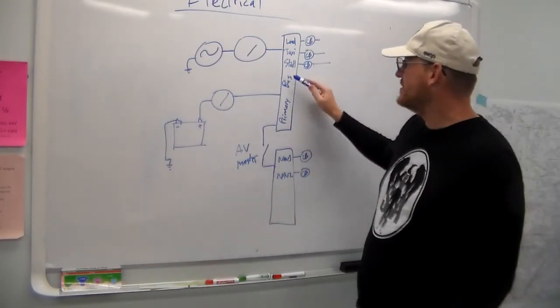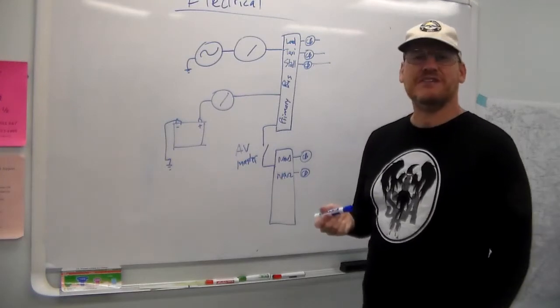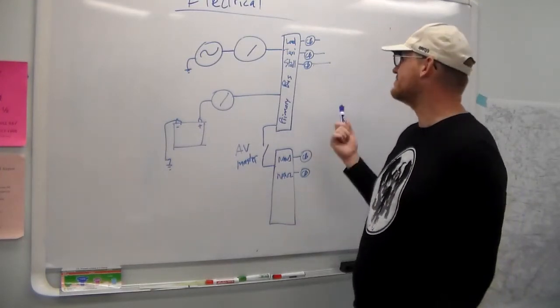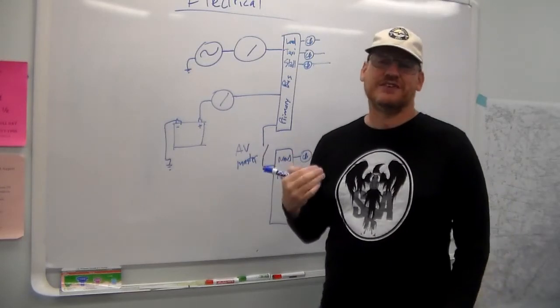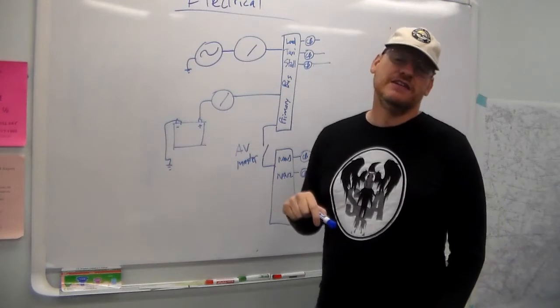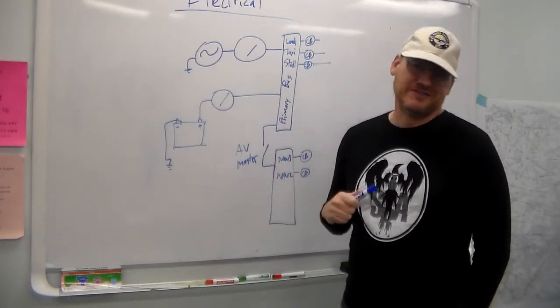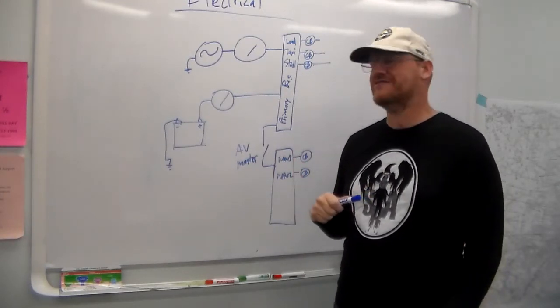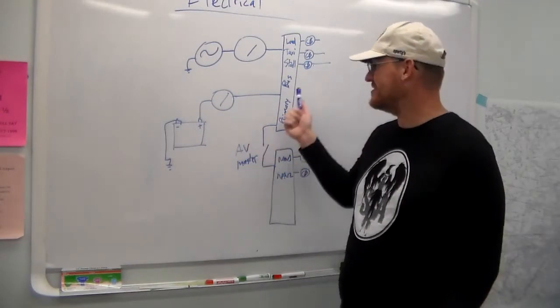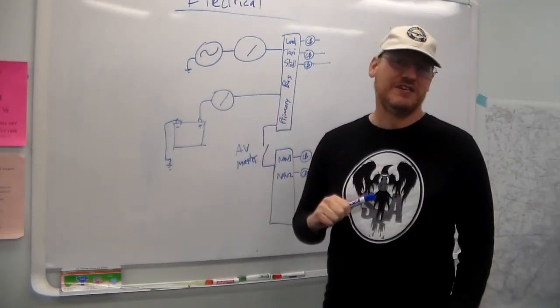Right? So your primary bus has all this stuff that when you turn the master on, you want to run, things like lights, obviously they're connected through switches, but you'll have stall warning. You'll have other electrical items that you need to run pretty much all the time.